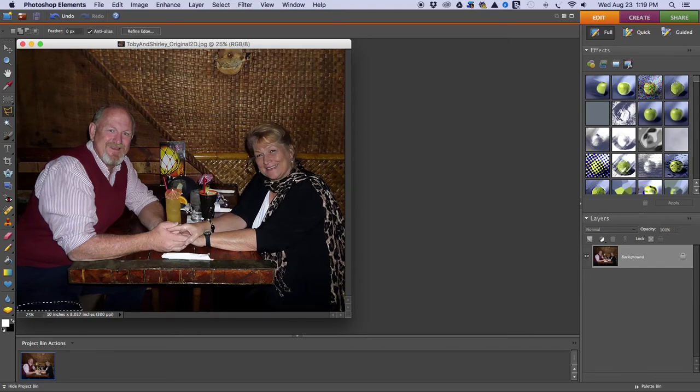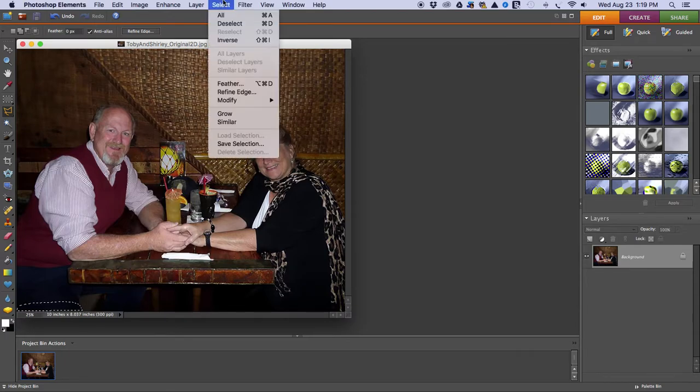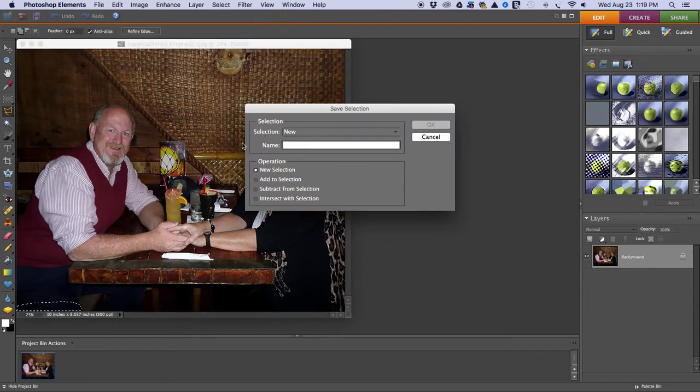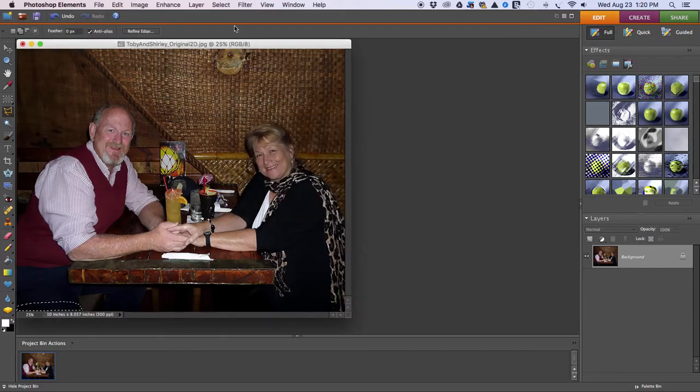Now the next step is to save that. I always recommend that you save your selection lines. Up under the select menu here, you have an option called Save Selection. Give it a numerical name. Use 3 digits, 2 if you want. It depends on how many depth slices you ultimately expect to do. I'm going to just leave myself an allowance here and go 001. And if you want to be more descriptive and call that Toby's leg or whatever you want to name it, it's totally up to you. And then that saves it.